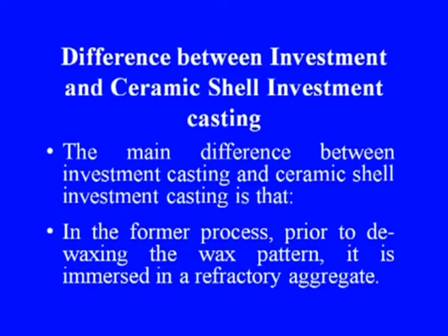The main difference between the investment casting process and the ceramic shell investment casting is that in the former process, prior to dewaxing the wax pattern, it is immersed in a refractory aggregate, whereas in the ceramic shell investment casting, a ceramic shell gets built around a tree assembly.